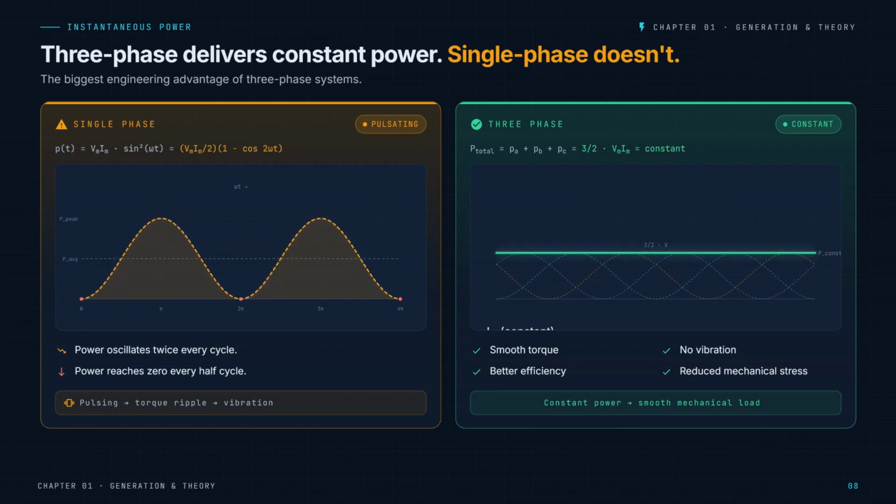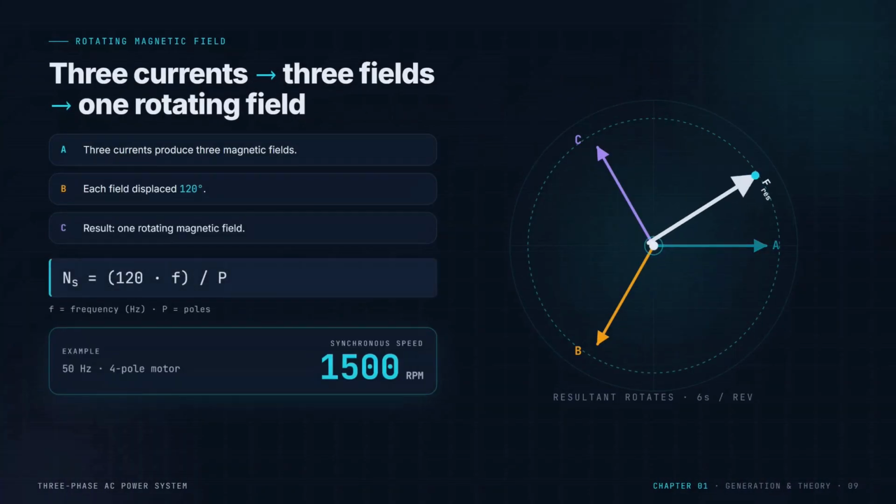of modern power electronics. Alternating current, on the other hand, changes direction continuously, allowing transformers to easily increase voltage for transmission and reduce it again for safe distribution. Higher transmission voltage means lower current for the same power transfer, significantly reducing energy losses in transmission lines. For this reason, AC became the dominant technology for national power grids.